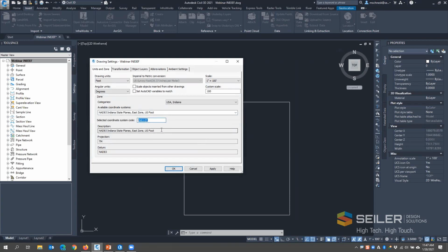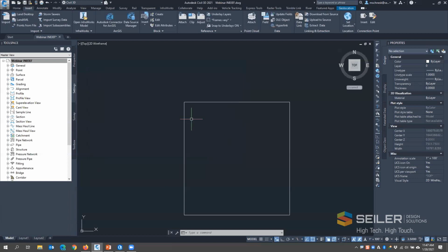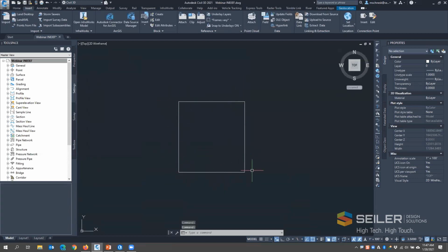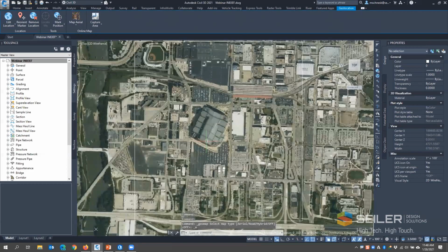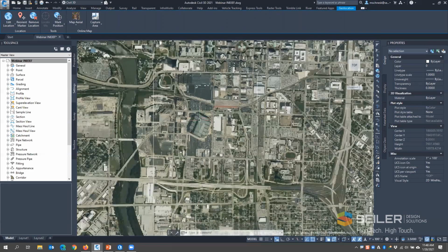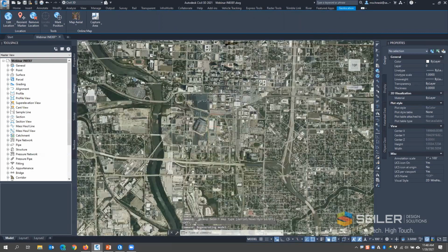So you must go ahead and set up a valid projected coordinate system in your model, whether it's UTM. I can't just use the Lat/Lon or LL, the WGS84. It's got to be a projected system. Okay. Once that's done, now I have a little area marked out for my area of reference. If I turn on my Bing mapping, you'll see that I am focused in on that Lucas Oil Stadium area in Indianapolis. So I'm going to go ahead and turn that off.